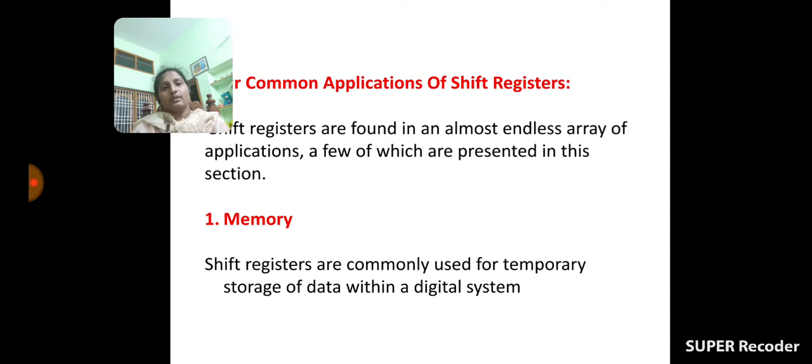For that purpose, in addition to the D flip-flops in the construction, it has two AND gates and one OR gate. Each and every flip-flop receives its inputs through the two AND gates and one OR gate. So in addition to the flip-flops, it also contains two AND gates and one OR gate for the sake of bidirectional shifting. Because it requires two AND gates, one OR gate, and one flip-flop for each bit, the circuit becomes complex.